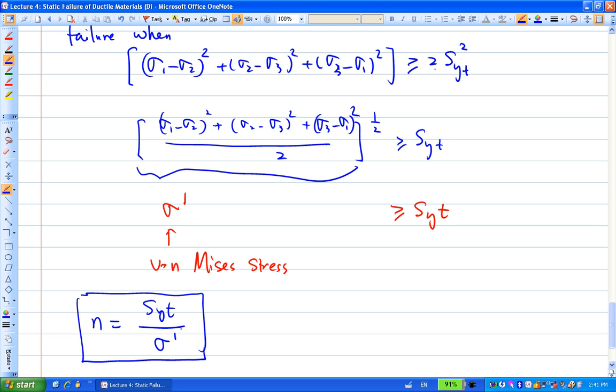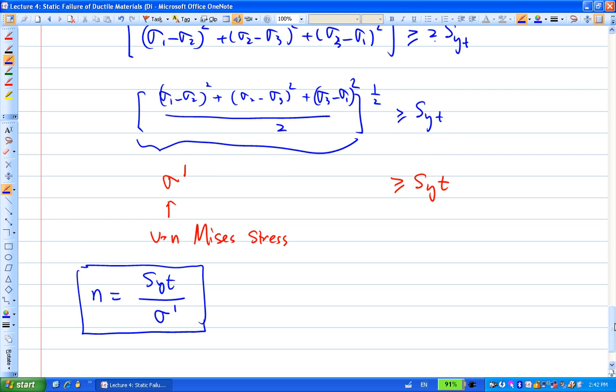Any questions? All good? Yeah, so I'm skipping one detail here, but you do need to know absolutely this portion right here. What is DE theory? You should also have some idea of where this is derived, based on the distortion strain energy. This is a formula in terms of sigma 1, 2, 3, which are the three principal normal stresses, right? This is the formula here.